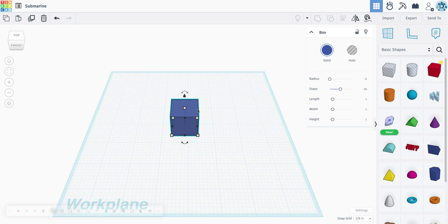The other thing you should notice when I click on the block is that these white squares appear. These white squares are showing me the edges where I can change the dimensions or the size of this block. Right now, this block is 1 inch by 1 inch. I know that because when I hover my mouse on one of the white corners, I see the measurements appear, 1 and 1.